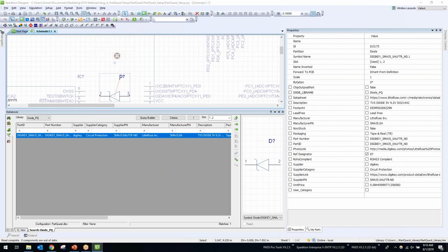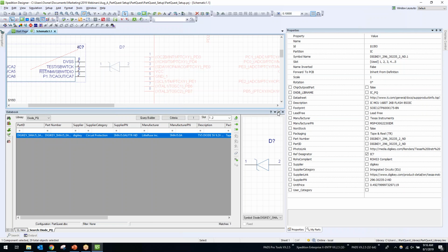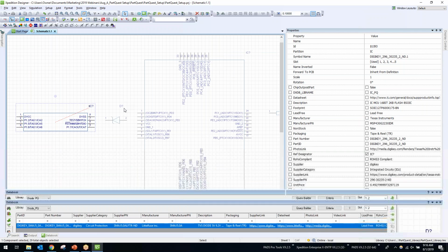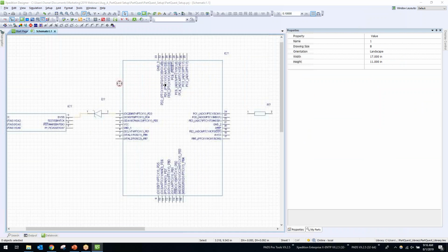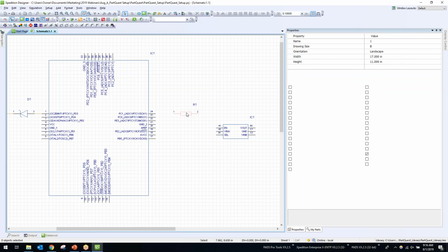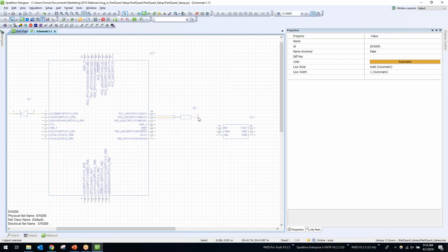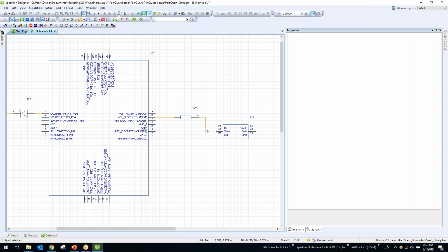All right, just really simple, generic library or schematic wiring techniques. I can do abutment. If I drag this pin onto each other and then off, you can see that purple asterisk shows that the connection's being made. It's going to create that connection for us. Or if I wanted to, I can right-click on these components or right on the pin, and then it's automatically going to start drawing the net for us.